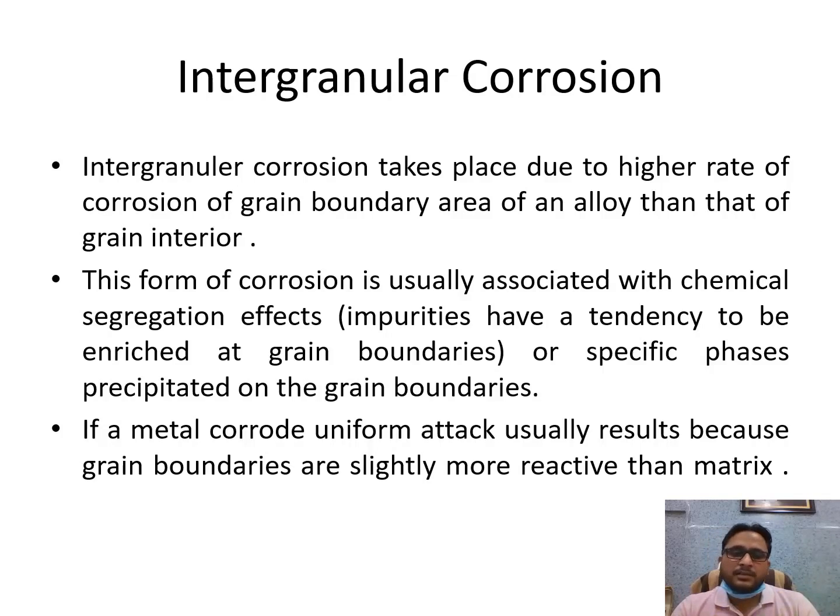mechanism of intergranular corrosion. However, this can be easily stopped if the size of the structure is not too large, because excessive deposition of chromium carbide near grain boundaries can be avoided by heating the metal uniformly. If we heat that structure uniformly, the chromium carbide that has been deposited near grain boundaries is again uniformly distributed within the structure.